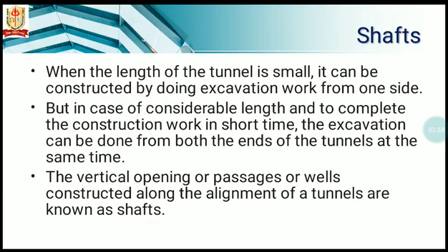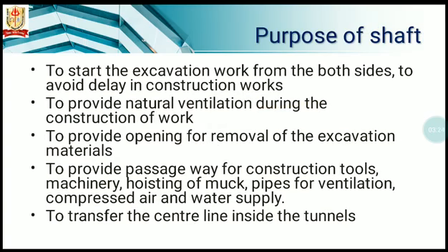Shaft. When the length of the tunnel is small, it can be constructed by excavation work from one side. But in case of considerable length, and to complete the construction work in a short time, the excavation can be done from both ends of the tunnel at the same time. The vertical opening or passage or well constructed along the alignment of the tunnel is known as a shaft.